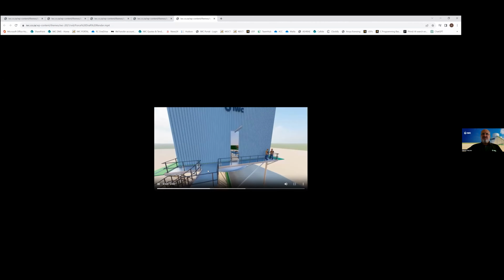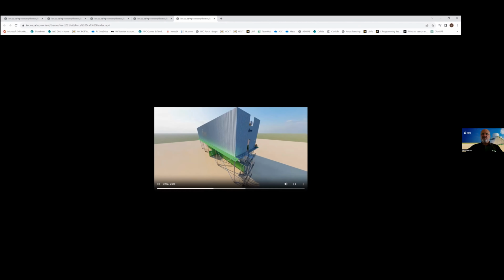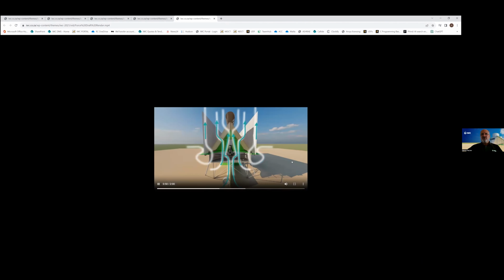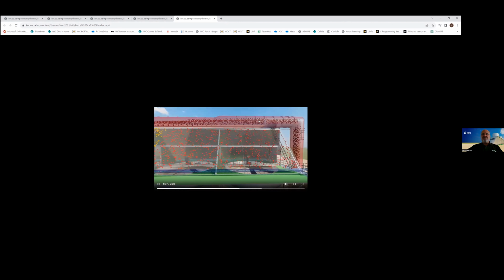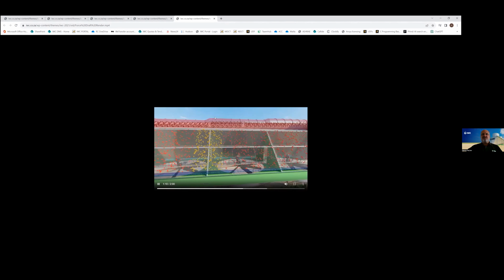Then you go outside, you see some special features, IWC features, which were developed at Stellenbosch University, this platform here and wind cross at the bottom. So how it works, the fans draw air from the environment and blow this air through these fin tube bundles. You see the typical streamlines of the air. Inside the system, you have steam coming from a steam turbine, and it goes inside the main steam duct, and then is distributed inside these heat exchangers, where it condenses inside the bundles and leaves the bottom as liquid water, and that allows the pumps to repressurize it for the boiler.